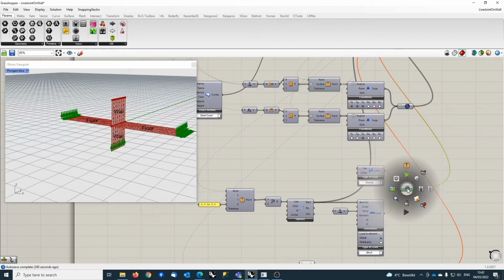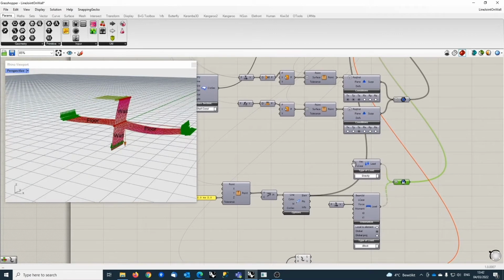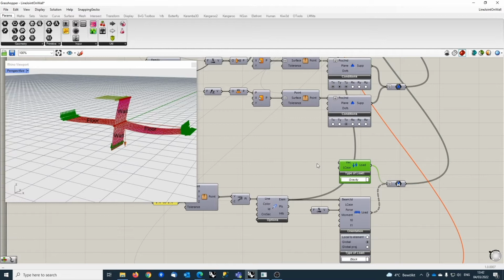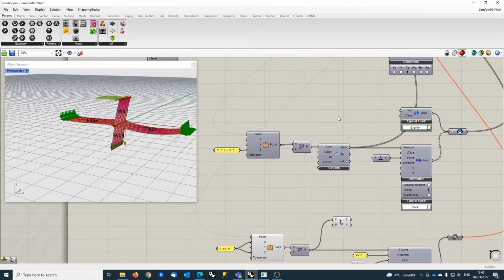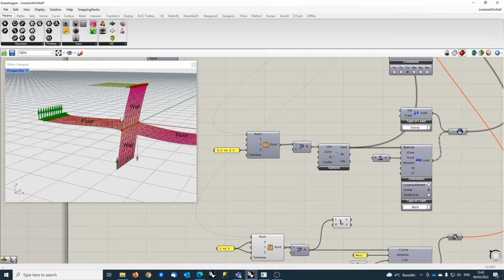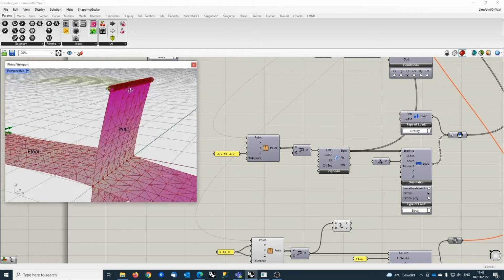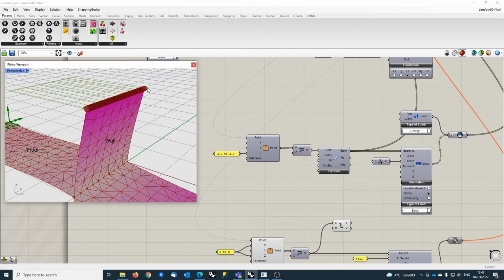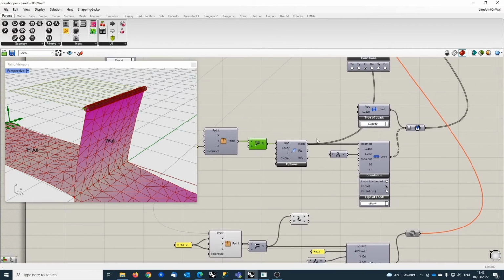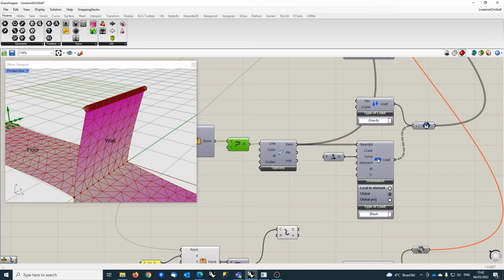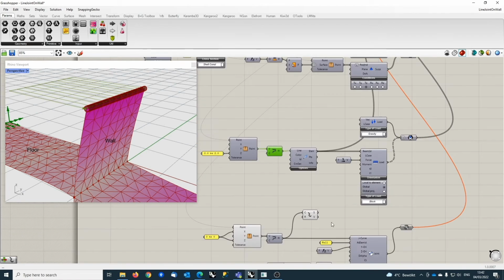Then we need some loads. For this I specified first of all dead weight, and in order to be able to demonstrate the effect of this line joint here, I placed here on top some beams and attached to those beams a constant block load.